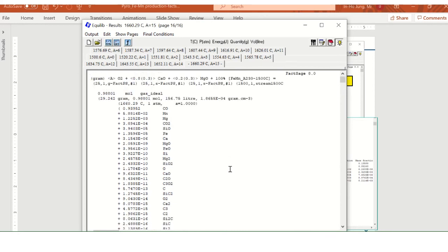So under this condition, the flux amount is not very good. That's what it means. Because we have to enter the proper flux amount and proper oxygen amount to have good decarburization of the ferromanganese alloys. And so this is the kind of thing where you have to vary the A value and the B value simultaneously to find the most optimum process condition. Okay, so you have to do this exercise, if you like, to find the good value.